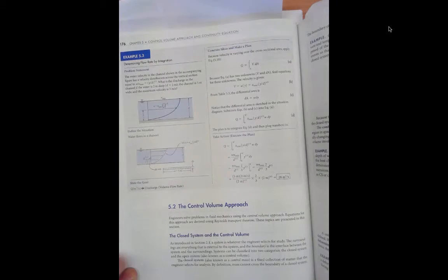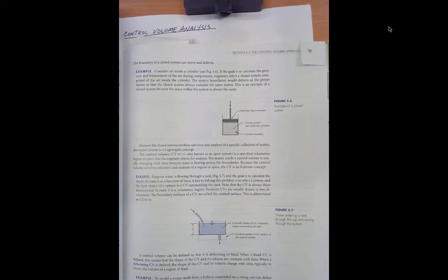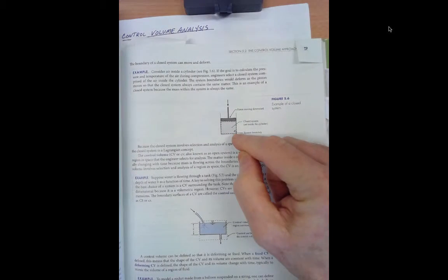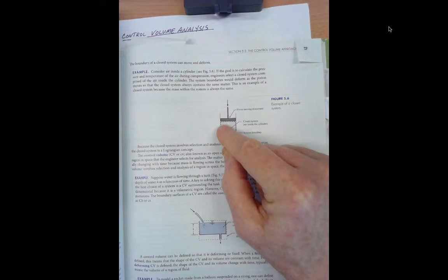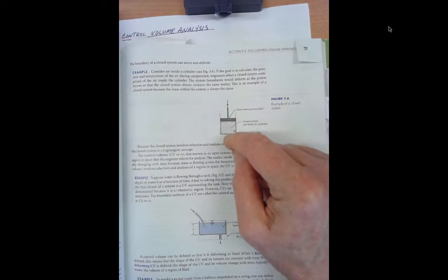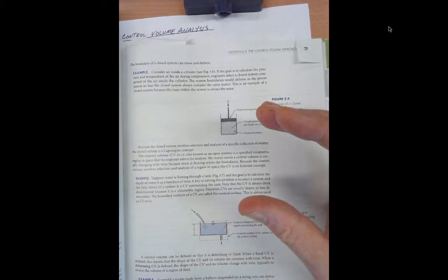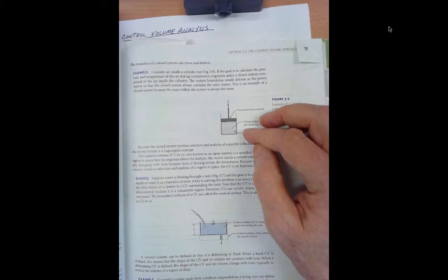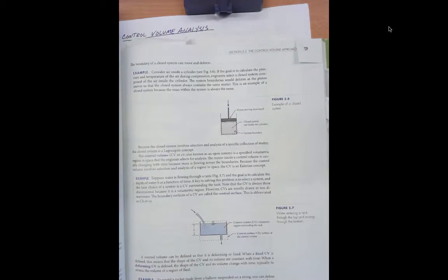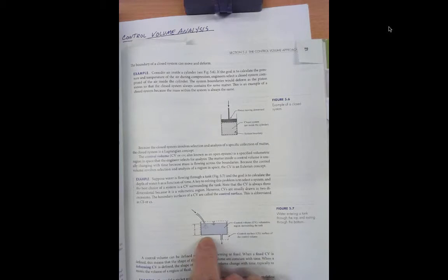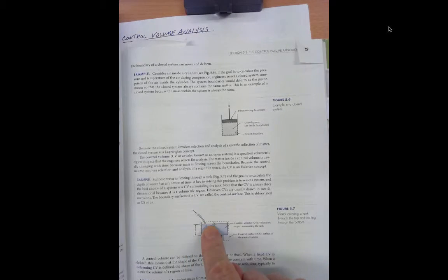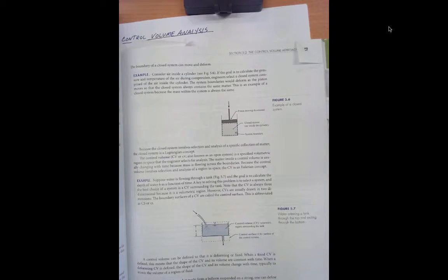and now we are to the control volume approach, and the idea of the closed system and a control volume. Again, the book does a really useful sketch where it shows a fixed amount of mass, and this piston is compressing downward, and so while the mass doesn't change, the system boundary or the volume does change. That would be a closed system. Another approach is to fix the volume in space. We don't let it change, and we keep track of what comes in and leaves that volume. And that fixed volume in space, also known as an open system, is the control volume.